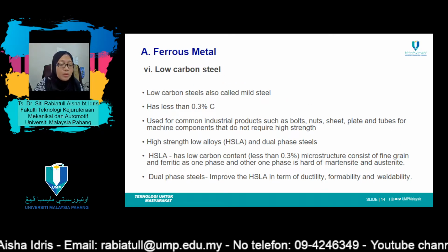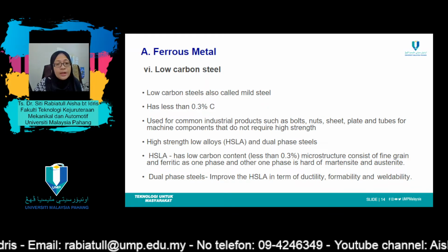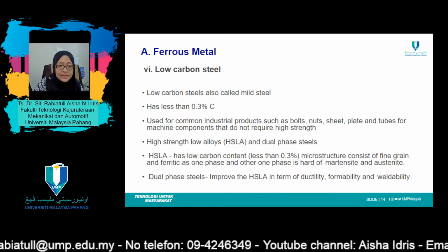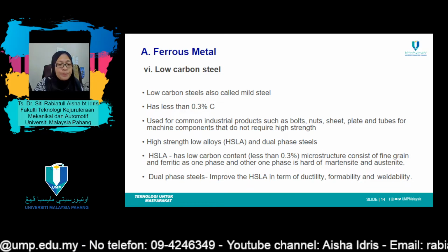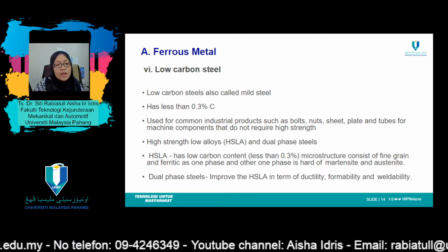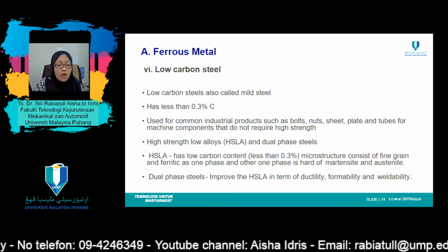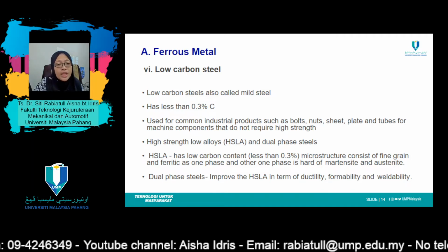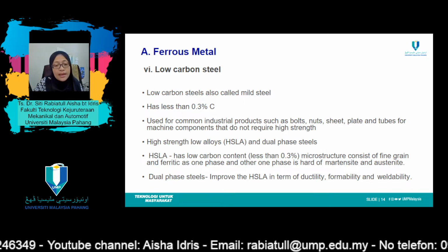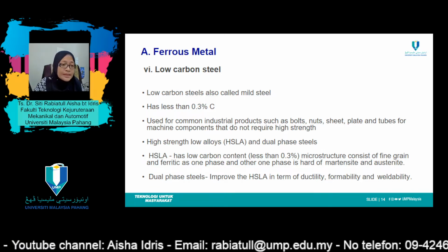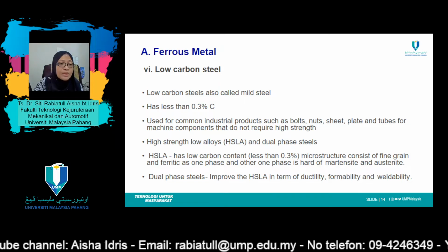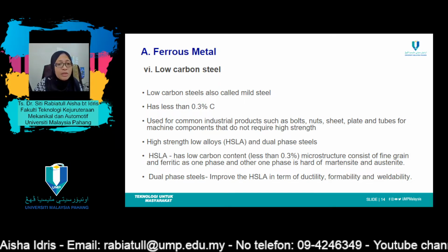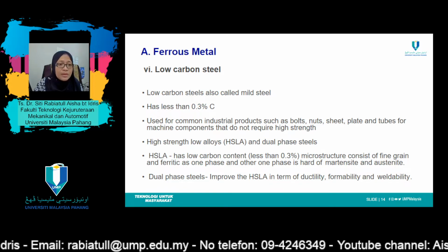Another group of low carbon alloys are the high-strength, low-alloy, HSLA steels, as they call them. They contain other alloying elements such as copper, vanadium, nickel, and molybdenum in combined concentrations as high as 10% and possess higher strength than the plain carbon steels. Most may be strengthened by heat treatment, giving tensile strength.